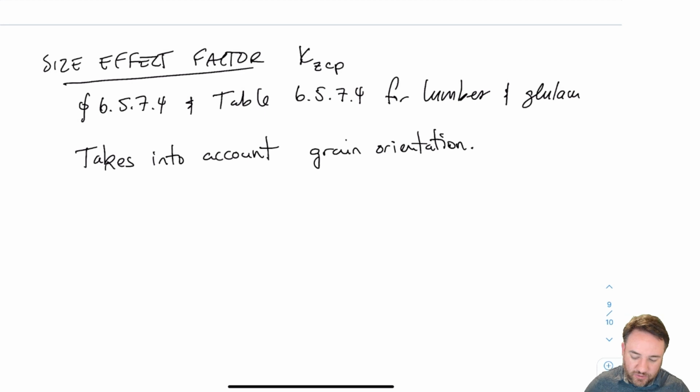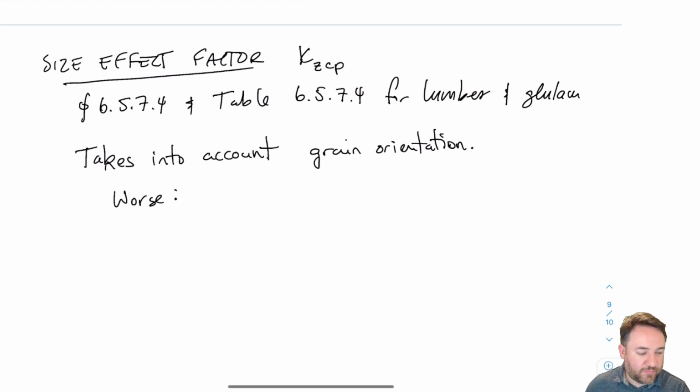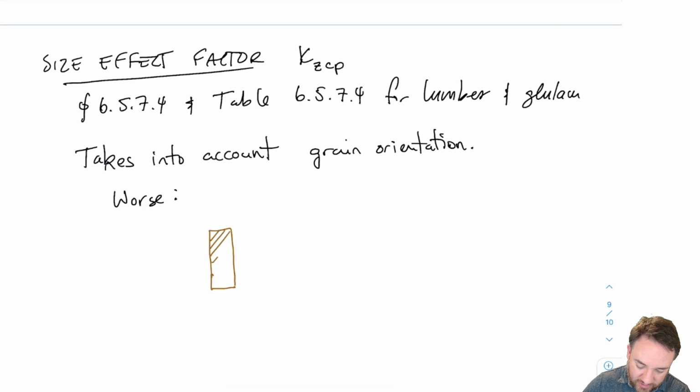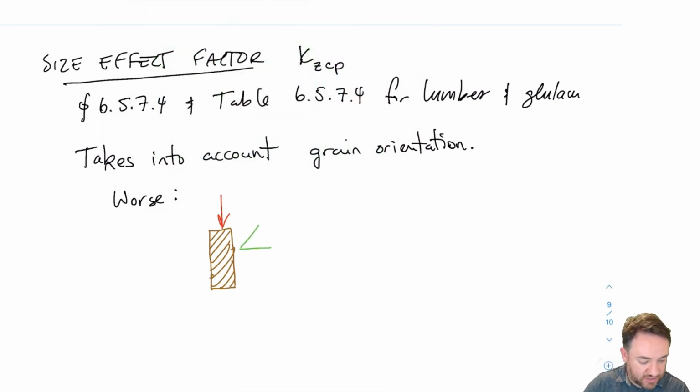So what they do is basically everything is calibrated for compression resistance, compression perpendicular resistance, to the worst case scenario for bearing. And the worst case scenario for bearing happens to be when the grain is at a 45-degree angle to the bearing. So something that looks like this. So if I have bearing on the top and this grain, I mean, obviously these are radial lines, so they're a bit curved. But if this is approximately 45 degrees, then that's the worst case.